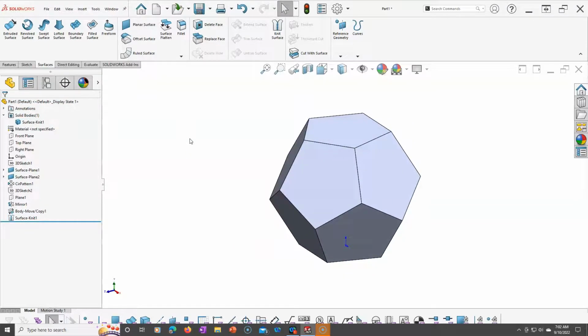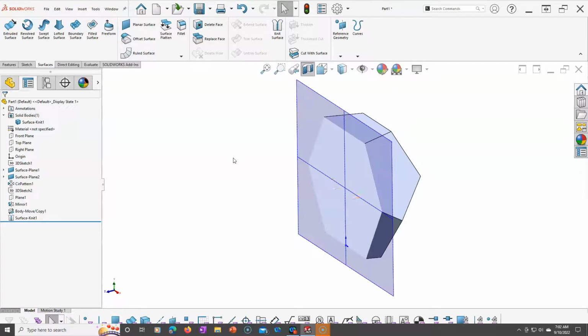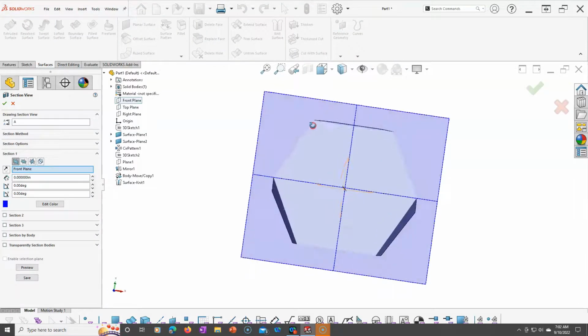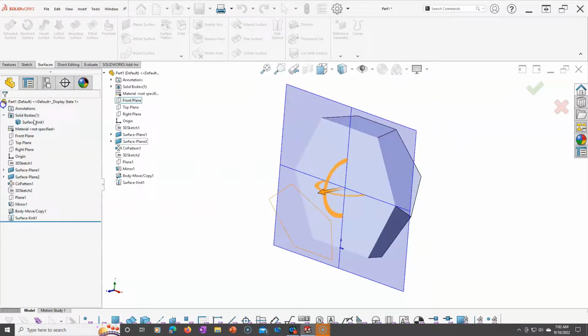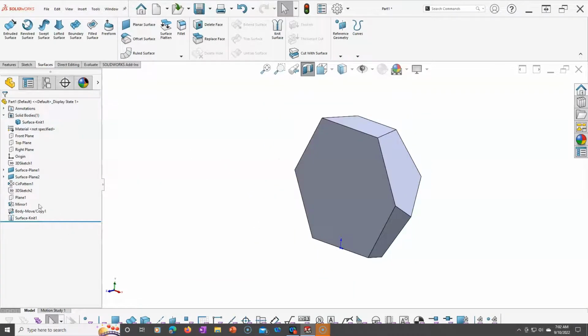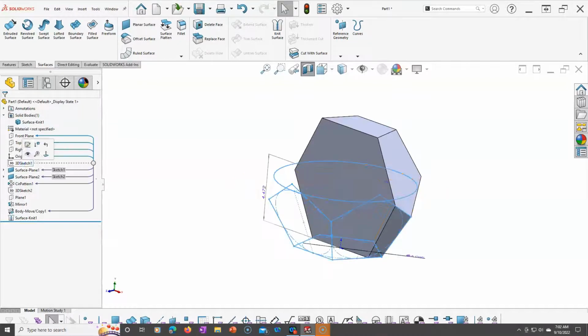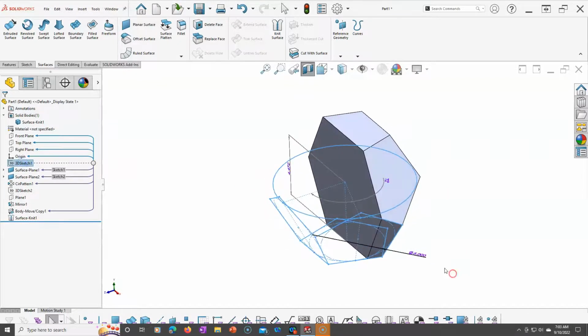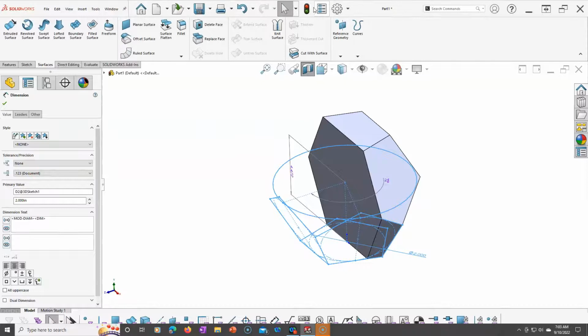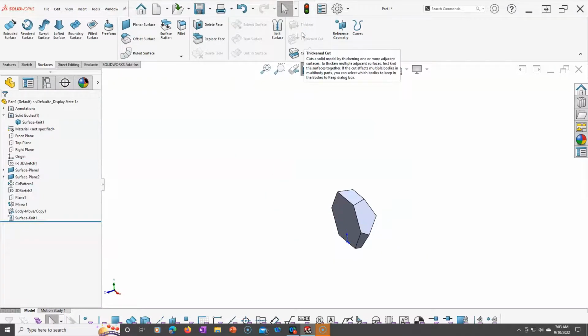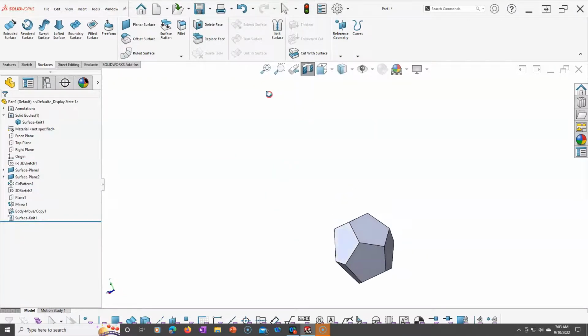And then we can tell that it's a solid because if I do a section view and look inside, it doesn't have those internal facets that we were looking for. So the test is always, I go back into the 3D sketch and I say instead of a 5-inch, I want a 2-inch, and we see if this rebuilds. Alright, so now we have that modifiable.